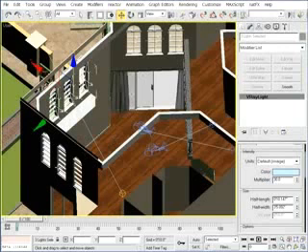There's quite a number of window and door openings in this room, so these 3 windows represent really a small portion of the total illumination, the total amount of skylight coming in. From experience in working with rooms of this size and with this number of openings, I know that a value of about 10 for the intensity multiplier will be a good place to start.